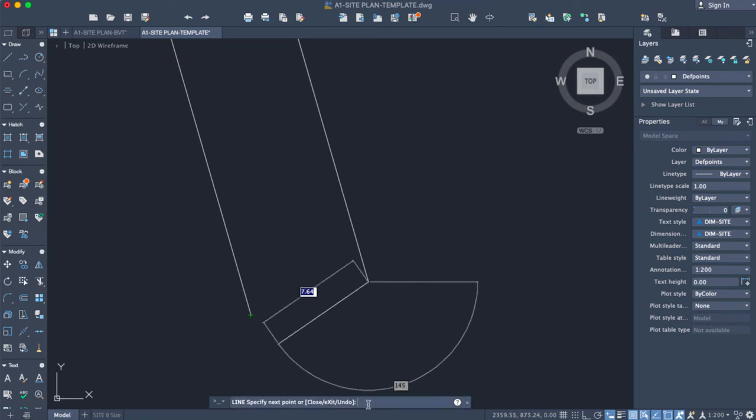For the next line, you can just simply bring it and close it up here, or you do have the option to type in the survey units. Again, it's just a good practice for you guys to do. I would recommend you guys to type in that survey unit. It's north 73 degrees, D for degrees, 59 minute 30 second east.